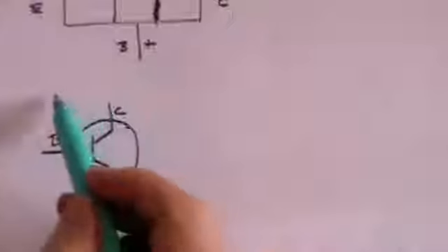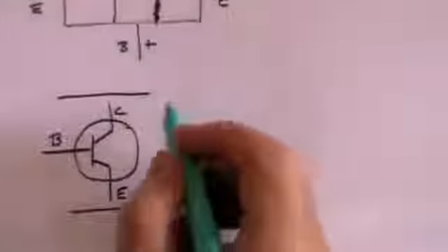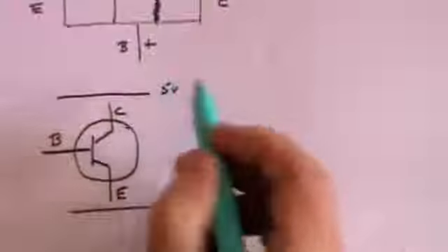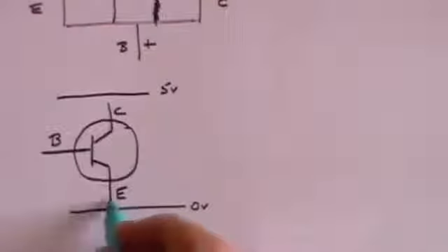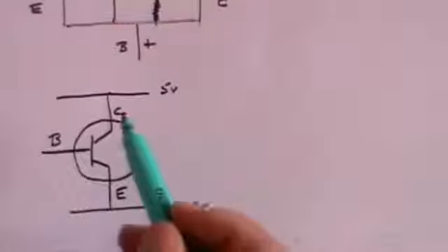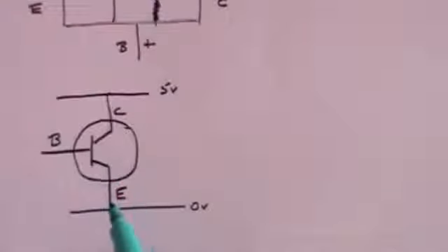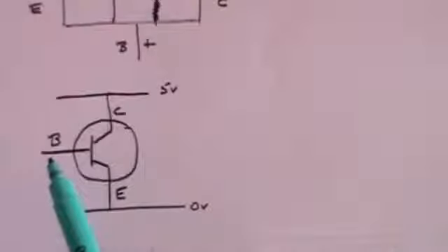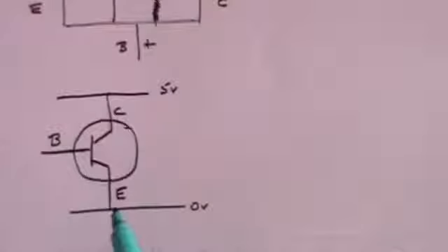And the same principle applies: it varies for different transistors, but let's say you have 5 volts here and 0 volts here, and we better join up the wires so that there is a link, and the position is that no current will flow. The electrons are going in this direction from the emitter to the collector, so the conventional current is coming in this direction down the voltage. So no current will flow through that transistor if there is no voltage on the base. But if you put a voltage on the base, then a current will flow through the transistor.